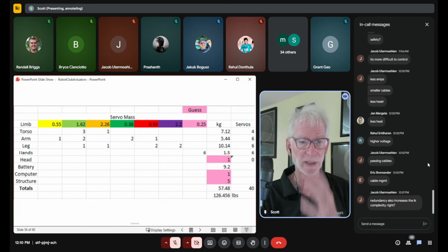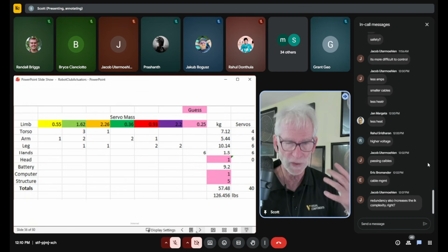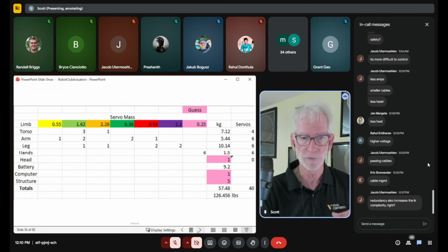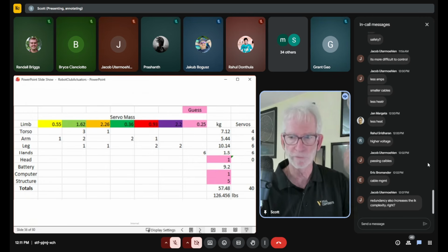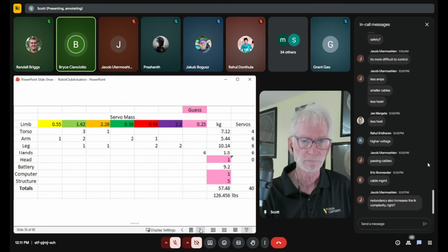It's been very hard to get under that, except for 1X, because they have a very different strategy. For an adult size, you can get one that's 35 kilograms if you're Hobbit size. But if you want to be full size, it's really hard to get below there. And again, it comes down to the mass of the actuators, because if you look at the overall mass of the actuators, you see they are a significant part, not only of the mass, but of the cost. So what different strategy are you referring to for 1X?